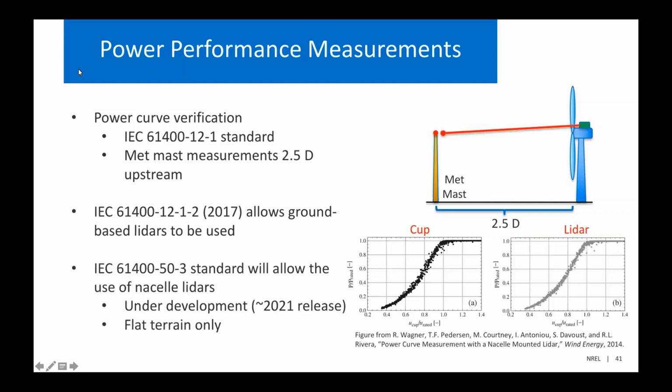And then the 61400-50-3 standard, which is being developed, will allow the use of Nacelle LiDARs for power curve verification. The expected release time is in 2021, I believe. But this standard will only allow the use of Nacelle LiDARs in flat terrain for power curve verification.